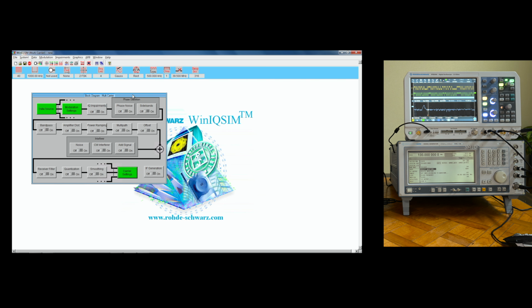Now let's try to send this signal over to the SMIQ. I already selected the SMIQ here. If I go to the target, the type of waveform generator I'm using, I'm told about the minimum clock rate, 1 megahertz, the maximum clock rate, 40 megahertz, already mentioned before, and the maximum sample length, which is 500,000 samples. I believe this is if you have the device with the standard memory, not the extended memory. I think I have 3 times as much memory because I have option B12 installed here. But anyway, we're seeing a maximum here. So I've got the right generator.